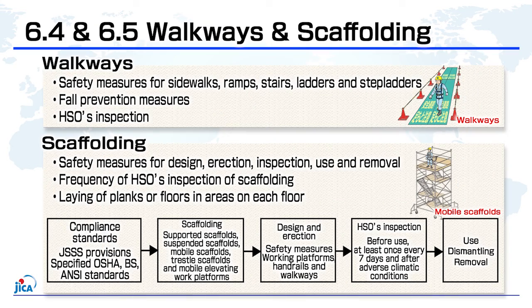Sections 6.4 and 6.5 specify safety requirements for pedestrian walkways and scaffolds for working. Section 6.4 stipulates safety measures to prevent falls on and from walkways and HSO inspections. In addition, ladders and stepladders can only be used as walkways when the HSO determines that they are safe. Section 6.5 contains requirements for compliance standards, design, erection work, HSO inspections, and construction of working platforms and walkways for scaffolding.